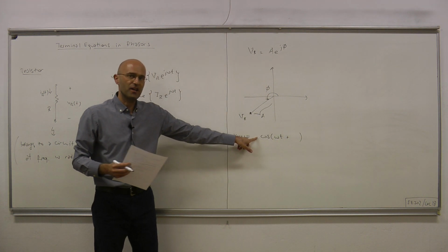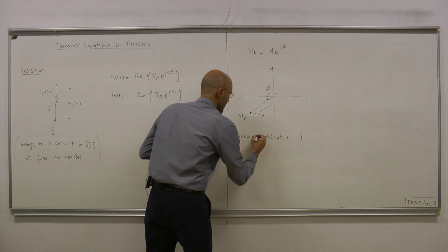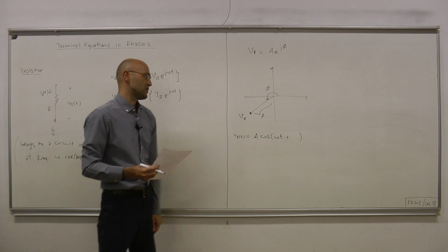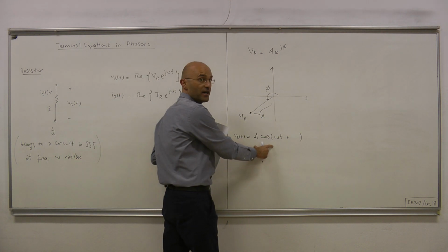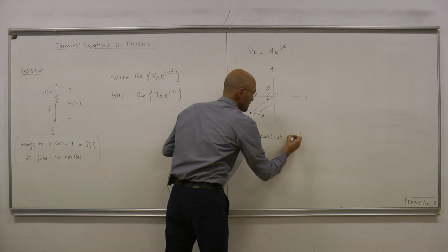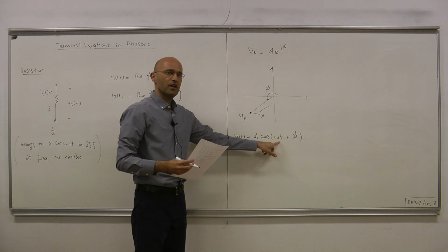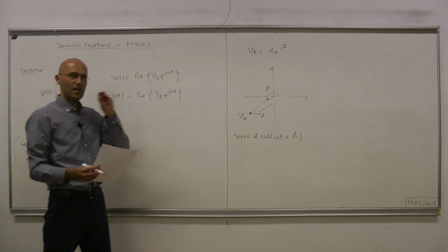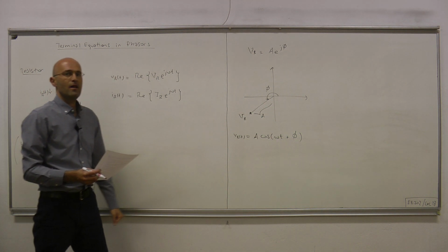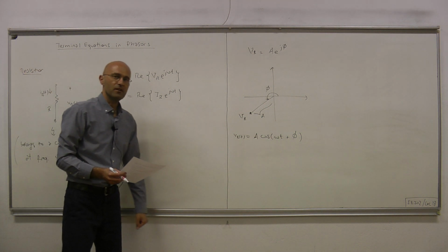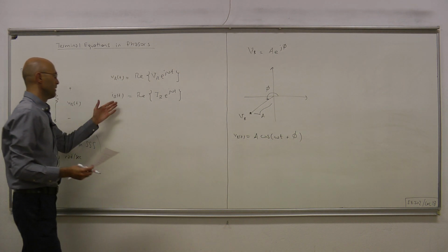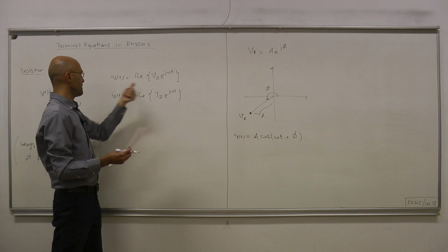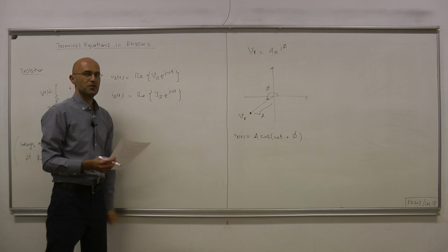The magnitude of that sinusoidal is A, because that's the magnitude of this phasor, that complex number, and the phase of that sinusoidal is the phase of that complex number, phi. As for the frequency, that's the operating frequency, and it's determined by the input or inputs that are driving the circuit.